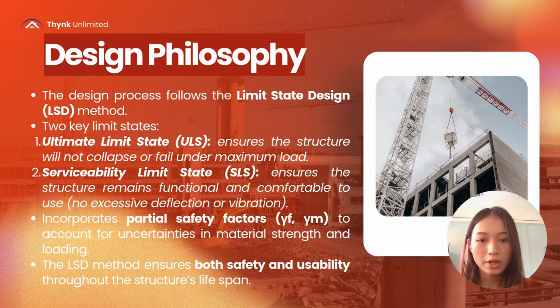It is to ensure the structure remains functional and comfortable to use, with no excessive deflection or vibration. It incorporates partial safety factors like γF and γM to account for uncertainties in material strength and loading. The LSD method ensures both safety and usability throughout the structure's lifespan.